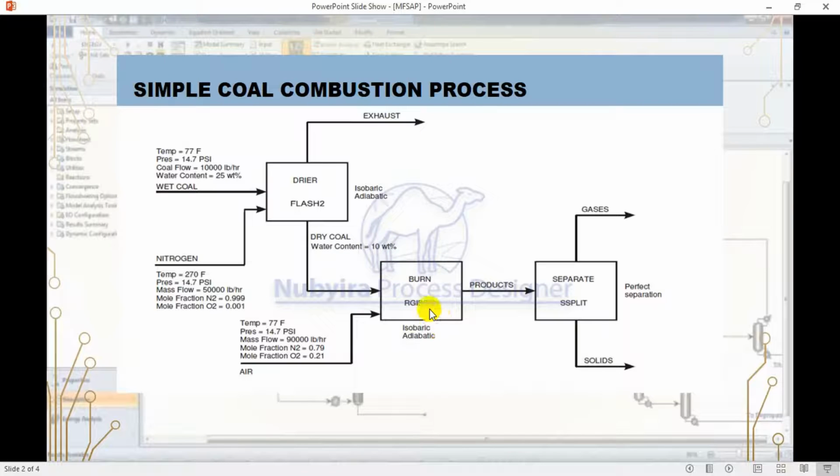Before that, there is a reactor which helps decompose the coal into elemental components such as hydrogen, nitrogen, and carbon, before it's burned through a Gibbs minimization process. So we model it as a chemical process, like reduction of the Gibbs free energy. When a reaction occurs, the Gibbs free energy of the product reduces, just like the burning of the coal.